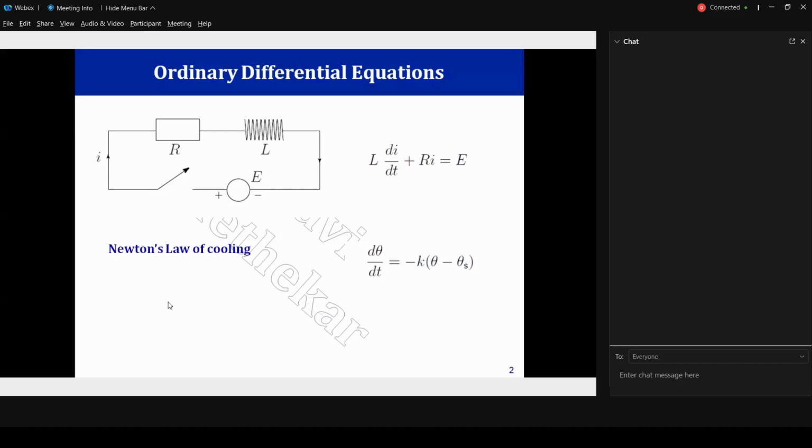First, we do a mass balance. The rate of incoming water minus the rate of outgoing water is equal to the accumulation. When we implement the continuity equation, we end up with a differential equation, that is dH by dt, where H is the height, equal to something. So it's a function of basically the inputs and outputs.